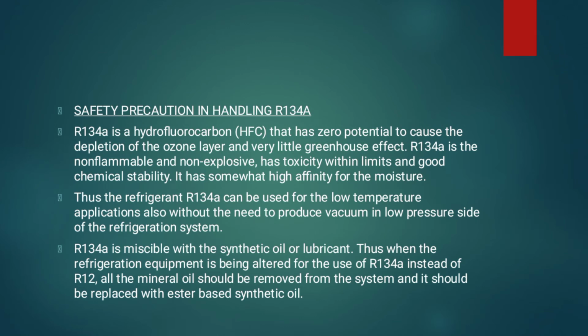Okay, so R134A is miscible with synthetic oil or lubricants. We all know na siguro, some of the automotive students know, that when we are refilling R134A refrigerant in the cooling system of a car or automobile, we typically need to put some oil in the compressor. So yun nga, yung mga synthetic oil and lubricants natin. All the mineral oil should be removed from the system and replaced with ester-based synthetic oil. Alright? So, ang gamit dito is ester-based synthetic oil.